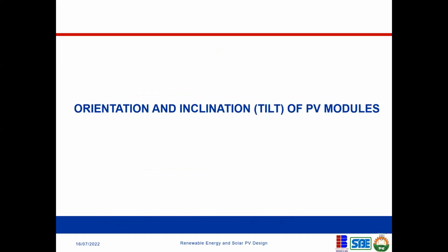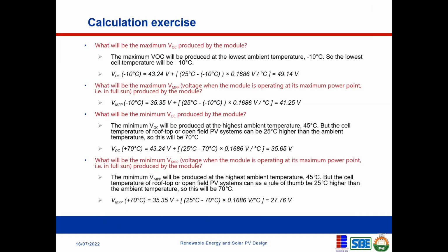Okay. Please, before we go, the question didn't specify at what temperature, because I can see you are using 25 degrees. Can you shed more light on that? Okay, so the question is asking us for the maximum voltage of that PV module, given the temperature of the location where it wants to be installed. Maximum open circuit voltage means that current is 0. What is the maximum voltage that can be gotten from that system?